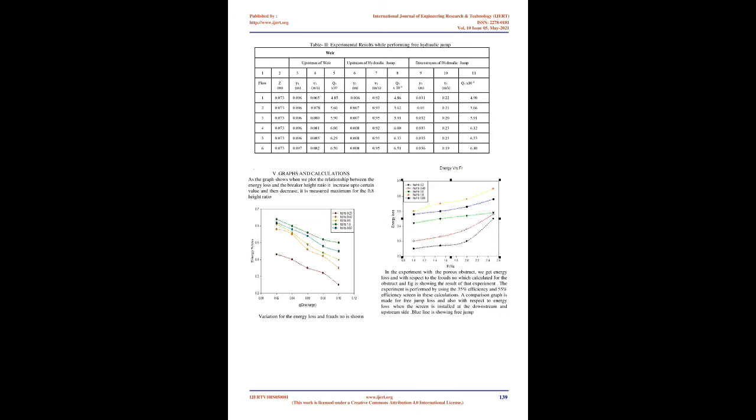Hydraulic considerations: topography, geology, type of dam, layout, and other associated structures, economic comparisons, frequency of usage, etc. Another author, Siddharth Upadhyay [3], proposed to restrict the location of hydraulic jump inside the stilling basin for maximum energy dissipation. In the paper titled Experimental Analysis of the Scour Profile Downstream of Flip Bucket with Change in Bed Material